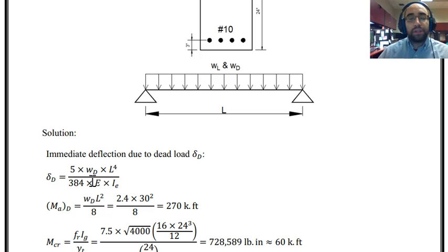In this chapter and example, we are looking at serviceability. It is deflections, and whenever we are dealing with deflections and serviceability questions, we don't include load factors. It's just the values of loads without any load factor or any of those load combinations that we looked at before.